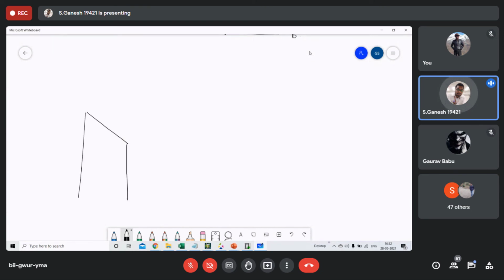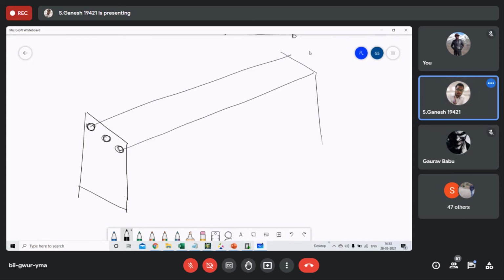When bar benders are making bar schedules, you see these bars. So 3 bars will be running throughout the section. This is an extra bar, so it will be bent and looped here. The same way on the other side, up to a certain point. Where you see this cut portion, that is your change in reinforcement. This is called a cut element, where you make a bend in the bar.